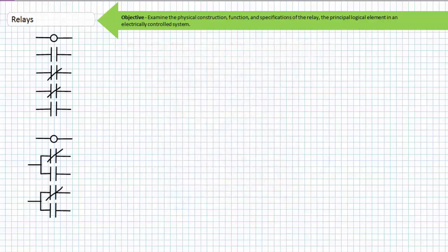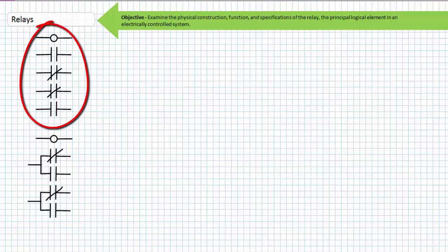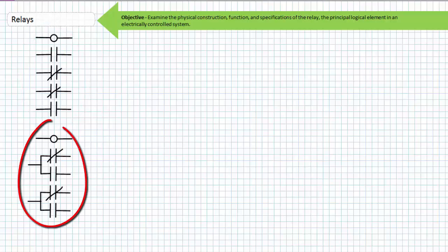Just like the contactor, a relay is typically characterized by a set of moving contacts that make or break a connection when commanded to do so by an electrically isolated, low-power control signal provided to the coil. Sometimes these contacts are electrically isolated single-pole, single-throw switches, as is typical for an industrial mini contactor relay. Sometimes these contacts are single-pole double-throw switches with a shared common terminal, as is typical for an IceCube relay, sometimes called C-form contacts or transfer switches.